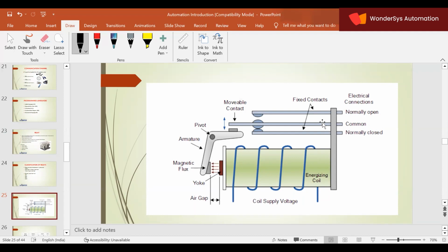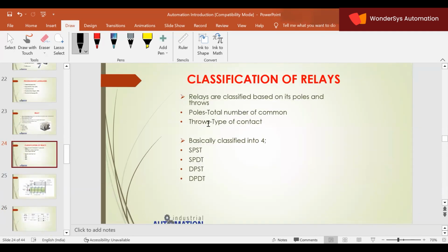Okay, now this is the input side of the circuit. Here at this side, either for NC or NO, we'll be connecting our lamps, motors, valves. Based on our requirement or based on the outputs, we'll be connecting either to an NC or an NO connection.